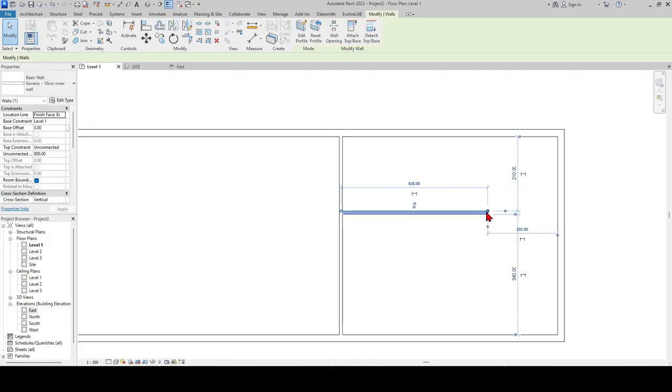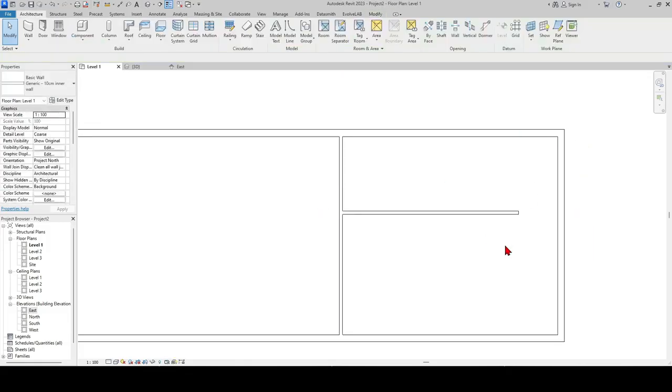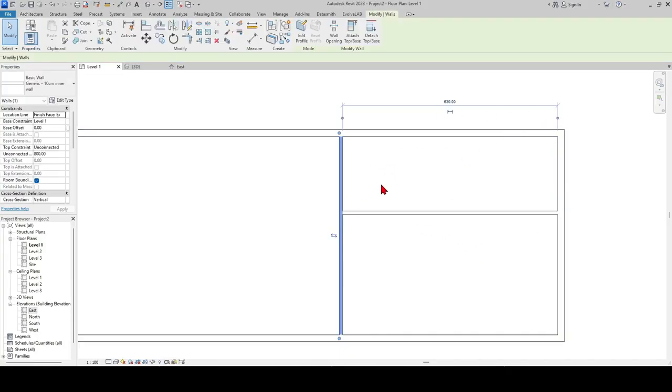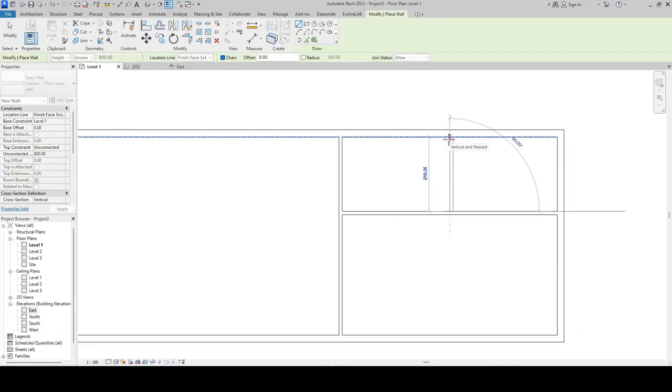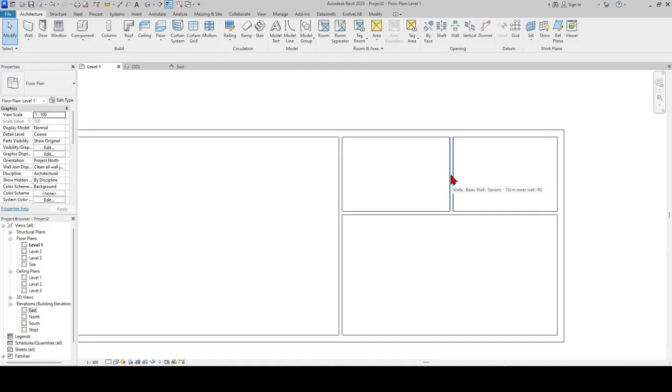You can adjust the length of the wall you draw by dragging it as you like. When you click on it, you will see its distance to other walls. Let's divide the room in half from the middle point of the wall, where the triangle sign appears. We also need to click on the measure command that we see in the upper part to measure the distance between 2 points. This command does not have a shortcut, but since we will use it frequently, let's create a